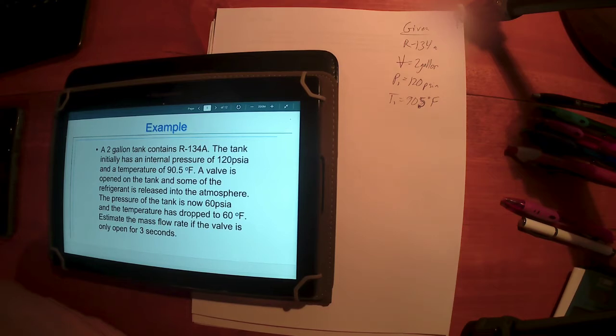That's in general pretty bad. It's not something you want to do. If it's ammonia, then that is actually quite toxic, and it's the reason we don't put ammonia in residential devices, because eventually it will leak out. Ruptures happen, leaks happen, and that's quite deadly. So we don't do that. We don't use ammonia for this purpose, even though it's a really good refrigerant. R134, though, you don't want to breathe it in, but we can put it in residential devices with a little less worry there.